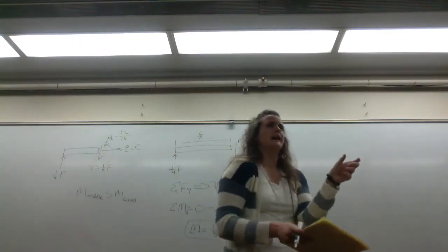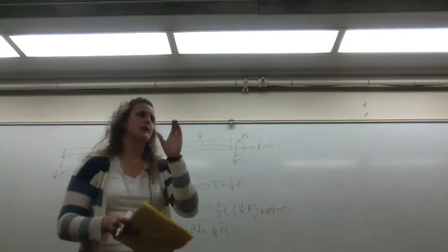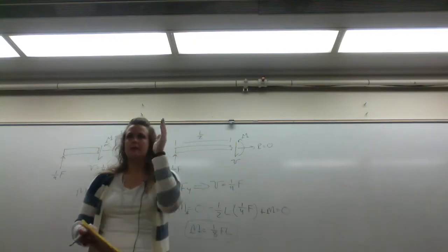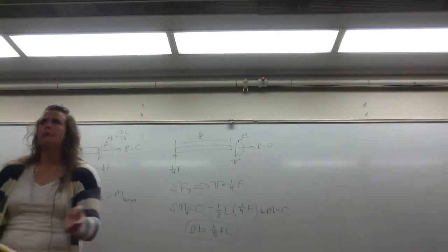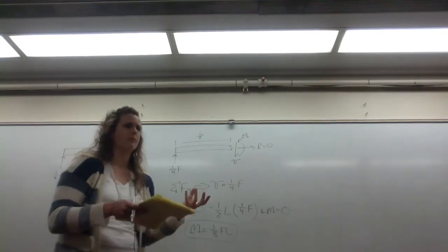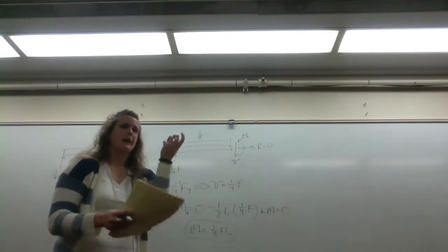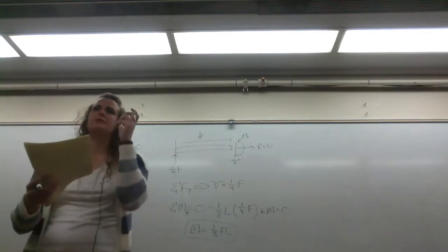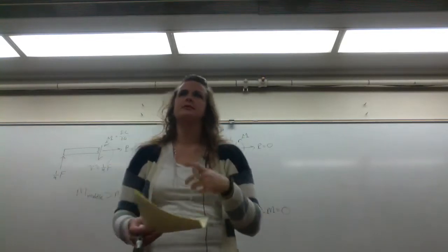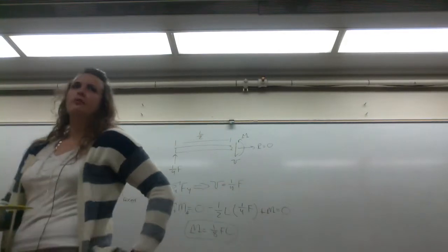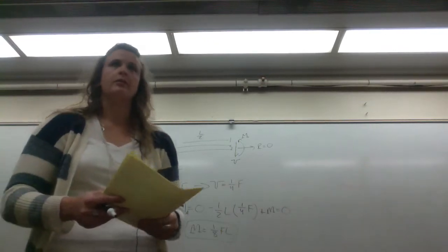This is when you discretize the beam based on applied loading conditions. When I say applied loading conditions, I mean applied forces and applied moments. Those can be distributed loads, those can be point forces, those can be moments, right? That's pretty much what we cover in this class. And then you make a cut and you solve for those internal forces within that section. And then we graphically represent our results. So that fourth step, we will kind of solve as we work through an example. Okay?